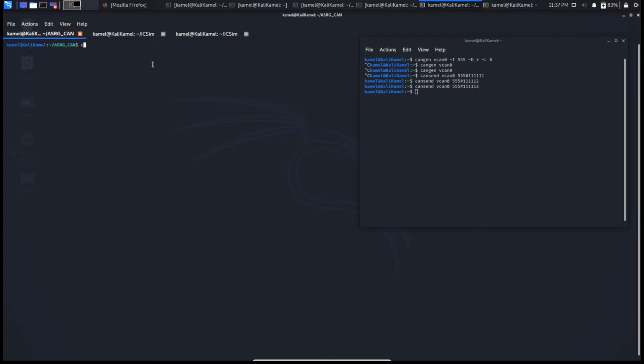And we're going to go ahead and say CANdump -L. Wait, no, you can't name it if you use the -L. You can name it. All right, sorry, I got ahead of myself. Okay, vcan0, right? This is all I'm going to do. I'm going to hit enter. Disabled standard output while logging, enabling log file, CANdump 2021. This is basically the date and the time. And it's opened a log file, and now this process is waiting and just grabbing all the CAN data and storing it into this log file.